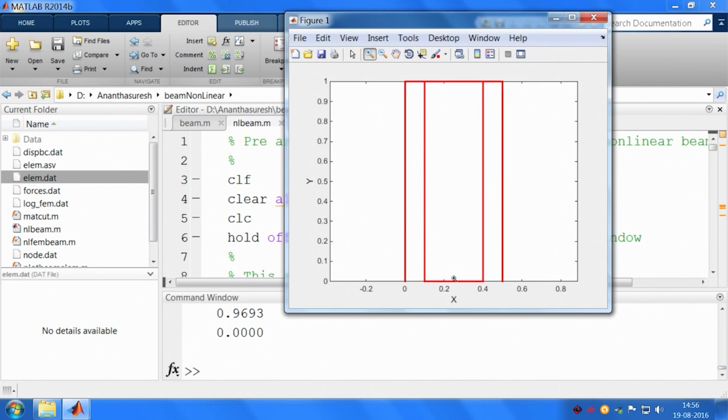So, for node 9, the degrees of freedom are going to be coming from the back, 27, because each node has 3 degrees of freedom. If you have 9 nodes, there will be 27 degrees of freedom. Those 3 degrees pertaining to node 9 are going to be 25, 26, 27. 25 in the x direction, 26 in the y direction, 27 the rotation.